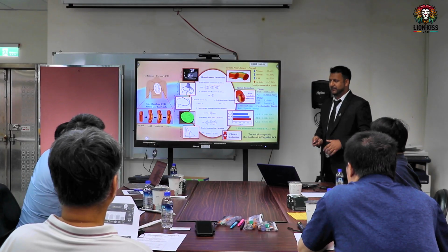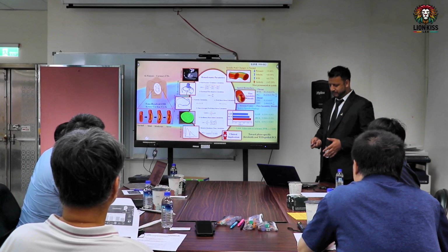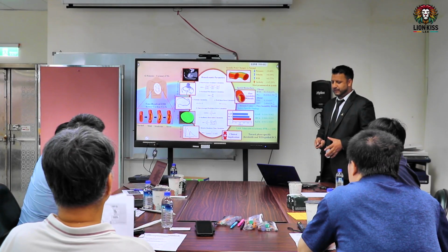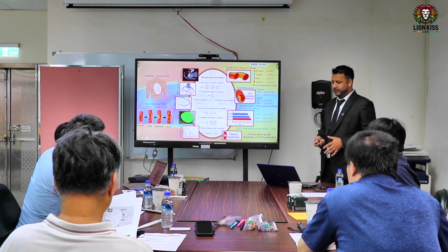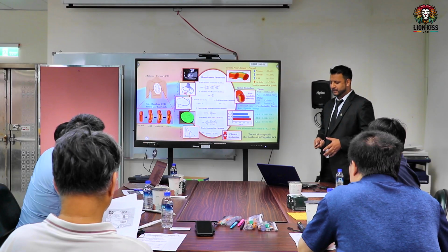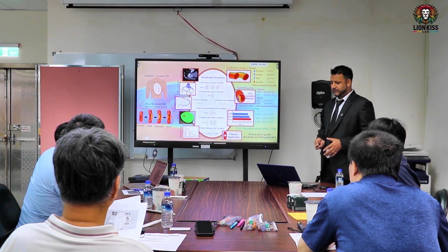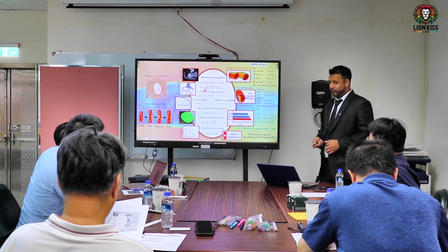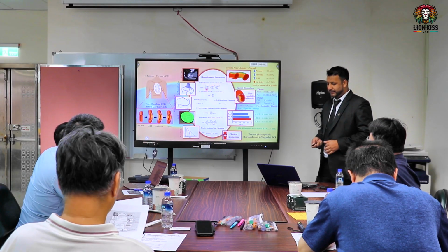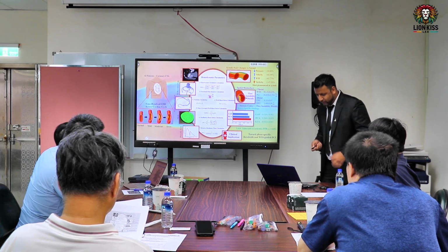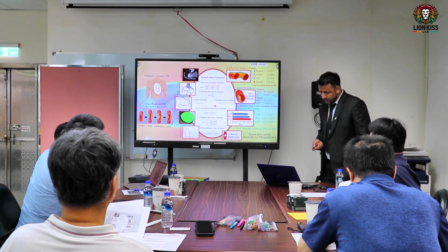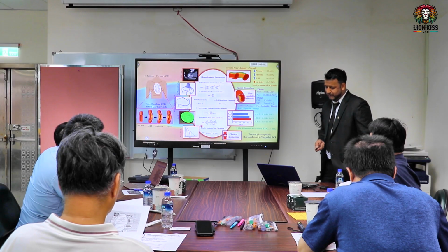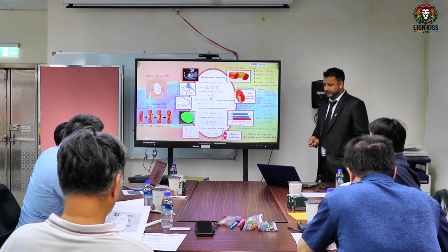So this is the graphical abstract of my paper that I published, in which we look at normal, mild, moderate, and severe stenosis. We take the DICOM images, reconstruction and vessel segmentation, meshing and pulsatile flow, and we analyze the hemodynamic parameters: wall shear stress, wall pressure gradients, fractional flow reserve, vorticity, time-averaged wall shear stress, oscillatory shear index, and relative residence time calculation.